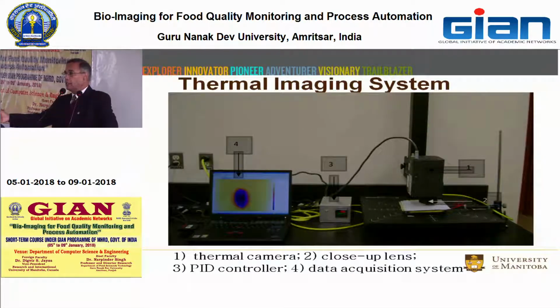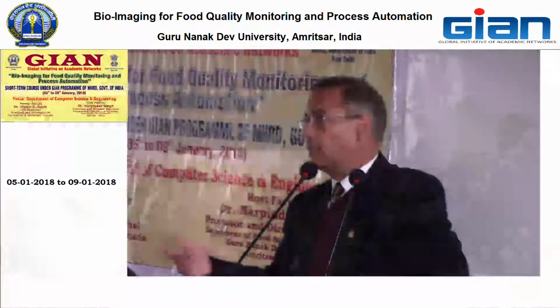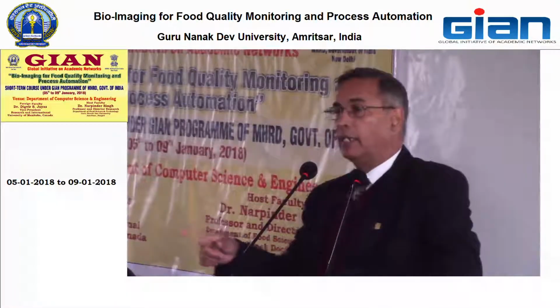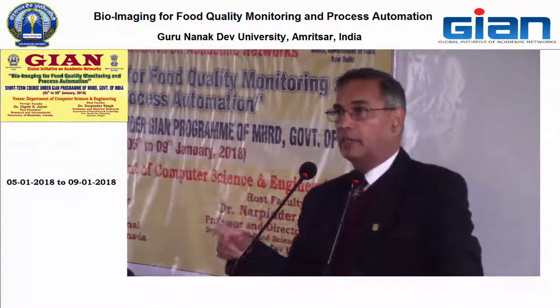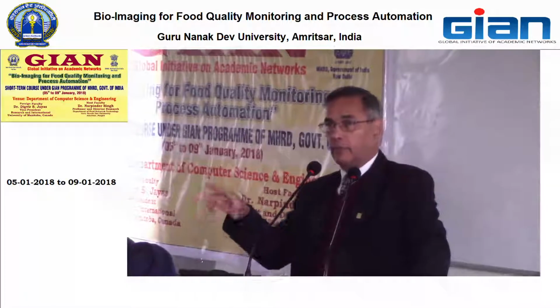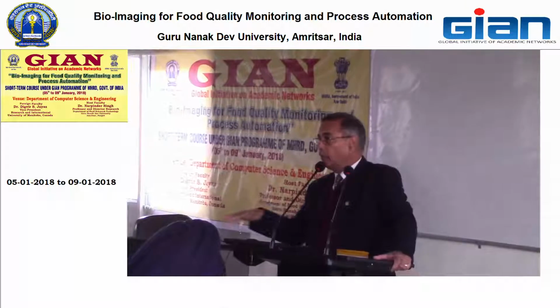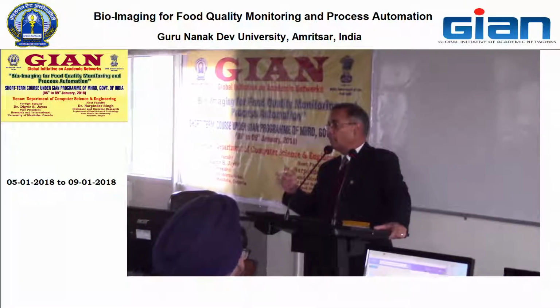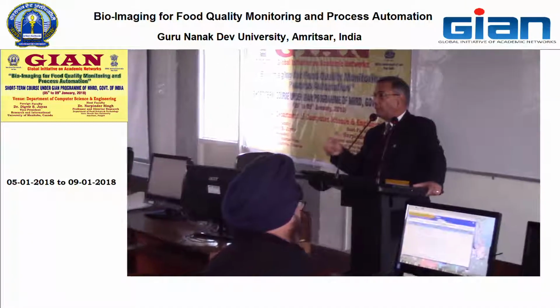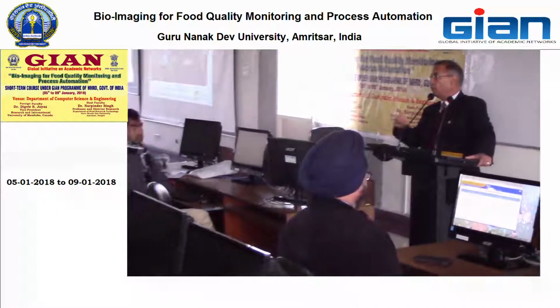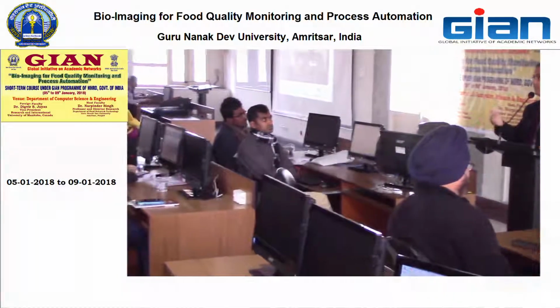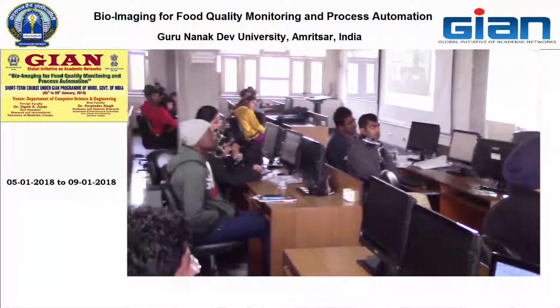You would bring this heater over the top of the sample for 15 seconds, move it away, take the image, and then do the analysis, and you'll be able to do the detection. So that's why the PID controller is needed. It has nothing to do with the camera. It is more for that heating system for this particular application. You could do the cooling or heating, because what you are trying to capture is the differential rate of heating or cooling, and that's where the difference is coming in the thermal imaging.